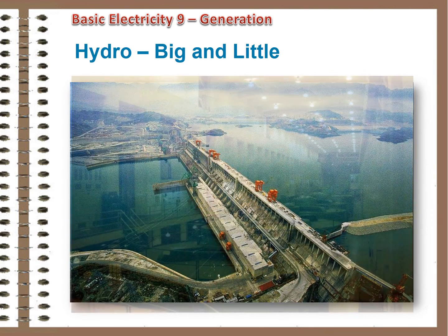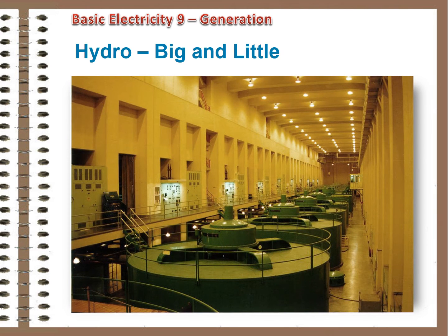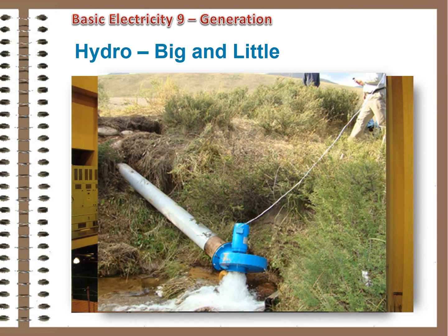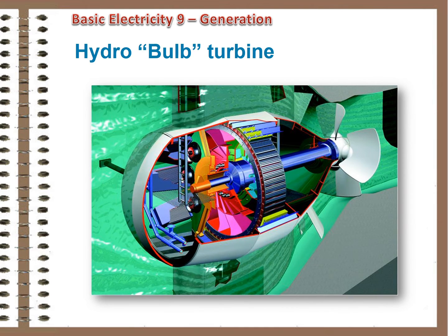The generators at large dam-based hydro stations may turn at 320 RPM with a 20-pole rotor. Small micro-hydro units run at 1,200 RPMs or higher, with proportionally fewer poles to produce 50 or 60 cycles, and everything in between. There are thousands of hydroelectric plants worldwide of all sizes. Some plants are even built inside self-contained bulbs driven by a propeller-like turbine and placed in areas of heavy current flow or tidal change. These units usually use a gearbox arrangement to attain high speeds for the needed frequency.